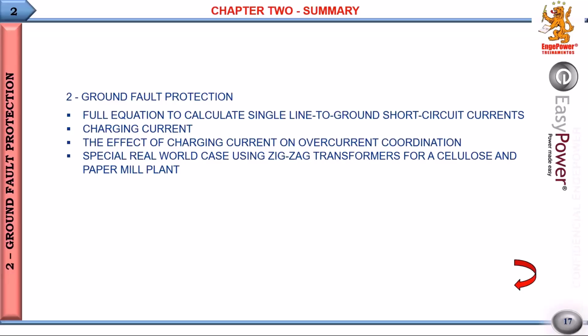That's the reason that for negative sequence currents, negative sequence protection at first instance is stator thermal winding protection, because we overheat.